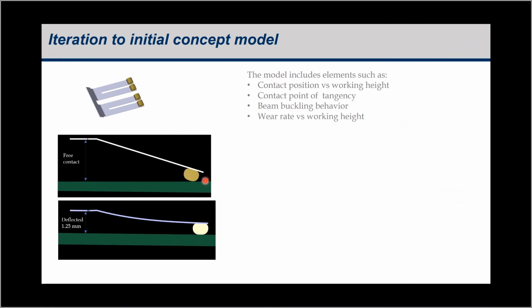So you see now the contact rotates as it's deflected. So choosing contact shape, right, and understanding how that contact shape is going to interface with the mating contact surface as that point of tangency changes, right, and then the contact moves. So what range of contact position do you need to accommodate? If it's an encoder application, what range of positional accuracy do you have to have?